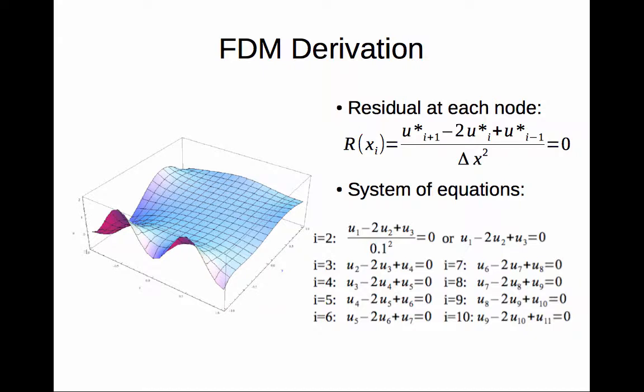And the powerful thing about finite differences really is that you can often write your own software. You don't need prepackaged software. Although there's a class of computational solvers called finite volume method. This finite volume method will take structured grids that have been warped into strange shapes, and it'll apply the finite difference equations using the correct geometry and physics on those warped but structured grids. Very similar to finite differences, fast solution and used in many fields.